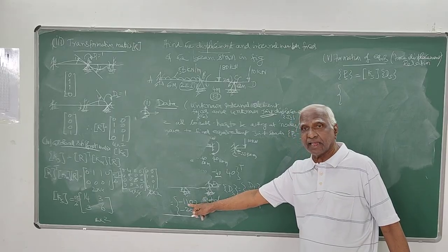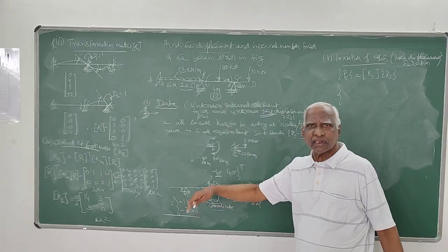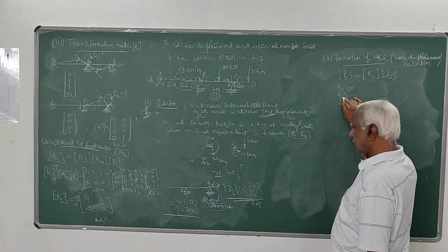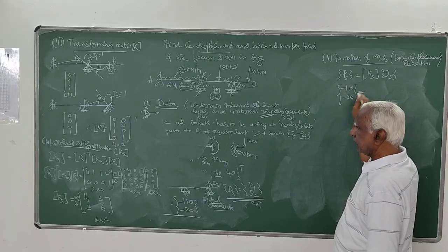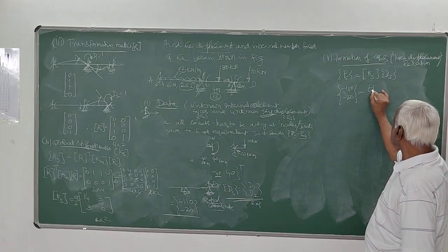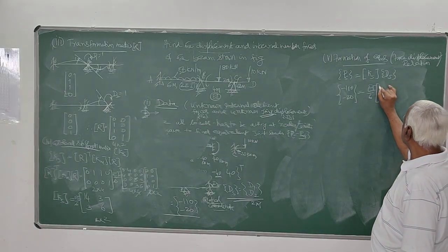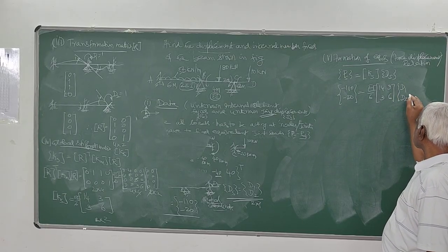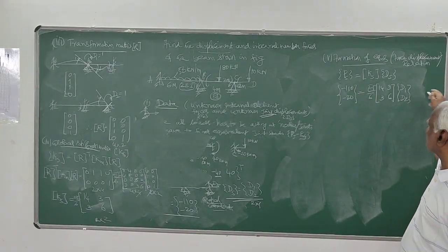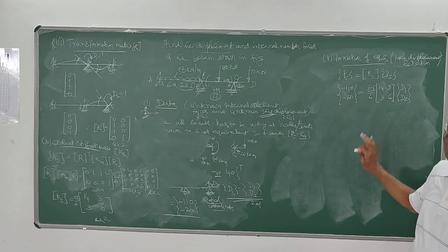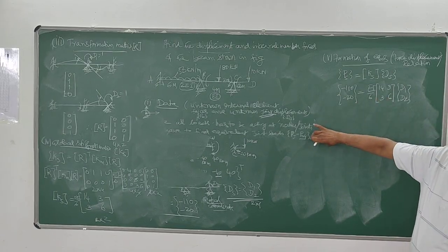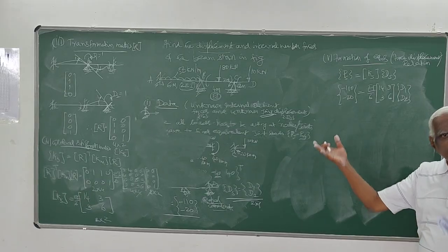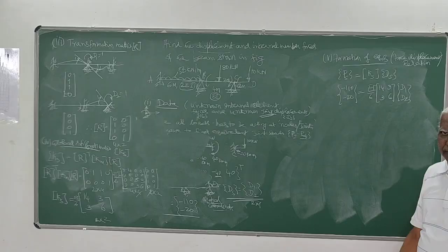Ps is minus 110 and minus 20, that is corresponding to external load. So that is minus 110 and minus 20. Ks we have generated here as 6 into 4336, and ds is d1 d2. That's the unknown. Now you have two equations. You can solve for d1, d2, or you can invert this Ks matrix and multiply by this ds. Either inversion or simultaneous equation solution. Either one you can do.